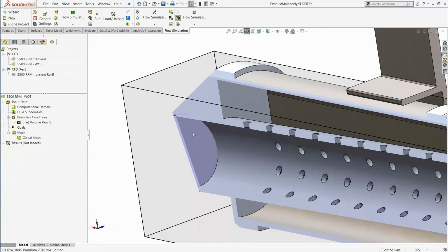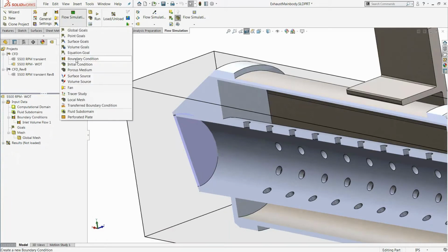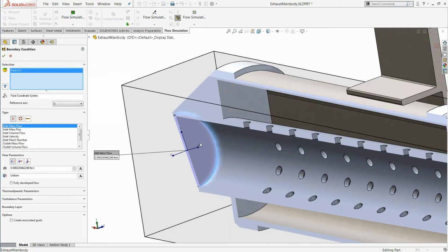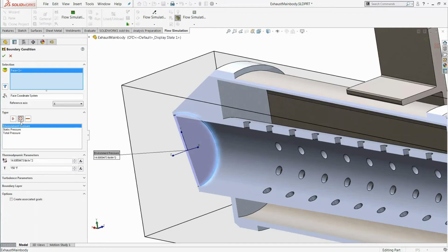So the air is going to come in from there, and then obviously it has to exit the muffler at the other end. And so I can do another boundary condition for this lid, but I probably don't know any other useful parameters like the velocity. And of course the volume flow rate would be redundant. So I need to put in something else at this lid, and in Flow Simulation what that is called is a pressure opening.